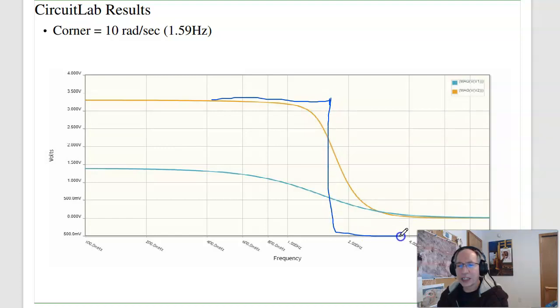Then the gain is supposed to drop off. Not exactly drop off, but that's the best you can do. If you constrain yourself to having n poles and the resonance cannot be bigger than 1, this right here can never go above 1. That's a Butterworth filter.